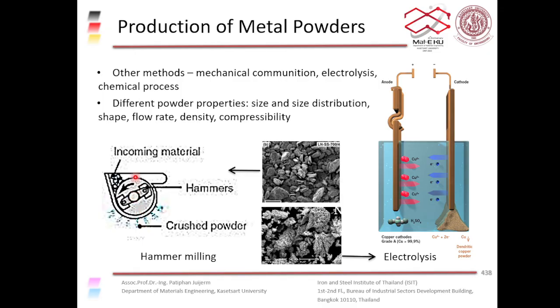You put in a big lump of metal, and you have a hammer mill with big hammers attached to a roller that keeps rotating and hitting that piece of metal until it breaks down into smaller pieces. When it is small enough to pass through the sieve, the powder goes through. If it's not small enough, it keeps getting beaten by the hammers until it is.